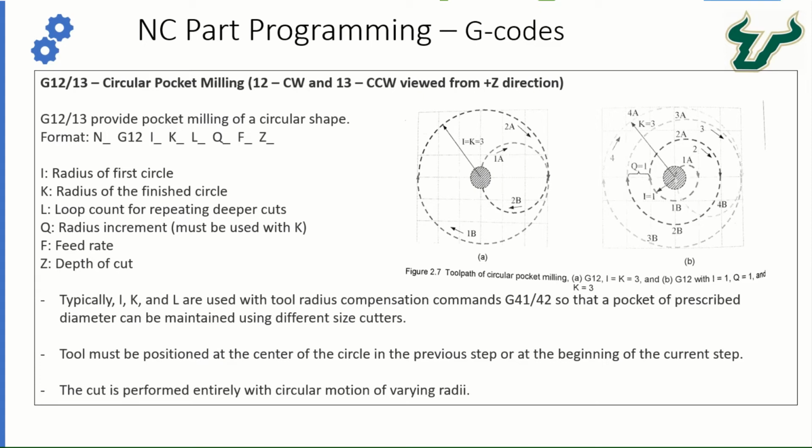All right, the tool must be positioned at the center of the circle in the previous step, or at the beginning of the current step, and then the cut is performed entirely with circular motion of varying radii.